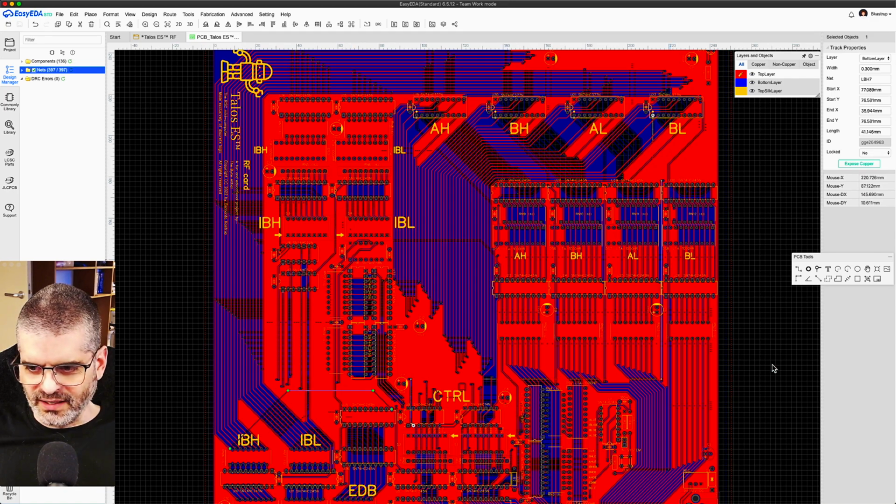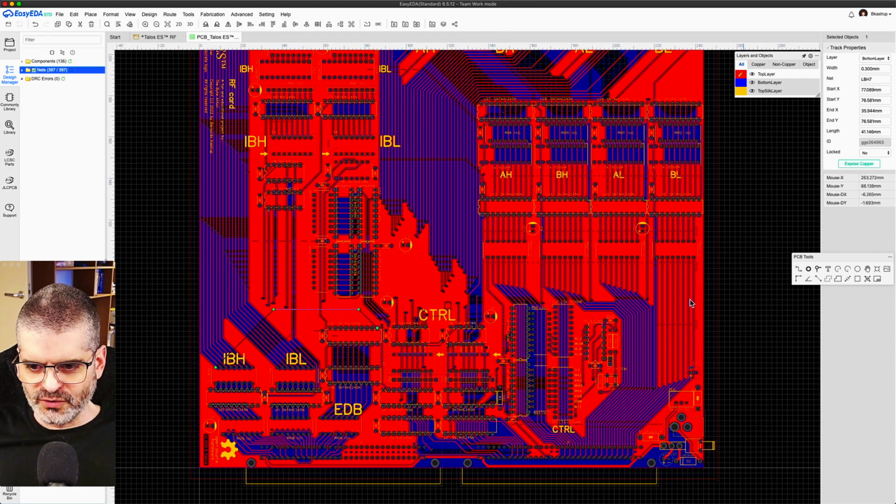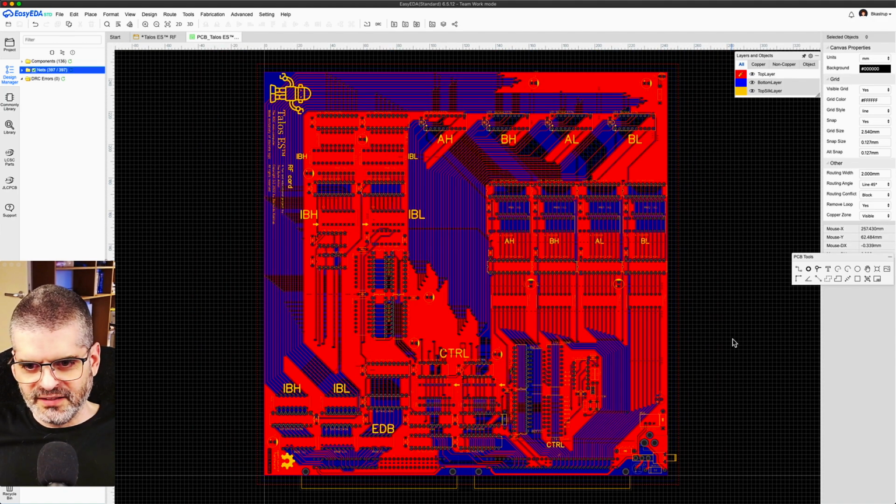Yeah, that's pretty much it. You try to keep the lines as short as possible, but not shorter. You try to keep them as far apart as possible. There is no need to crowd them close together if you have the space. You just increase the chance of crosstalk if you do that. Yeah, that's it, ladies and gentlemen.